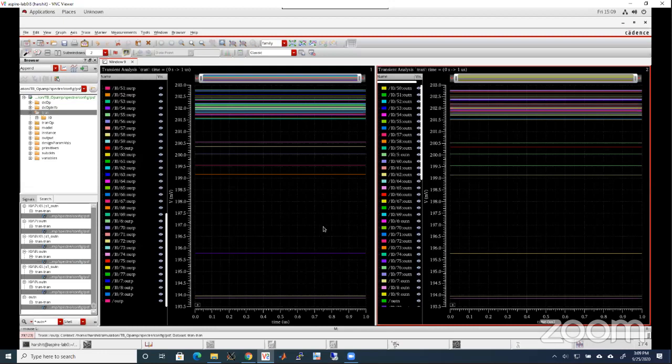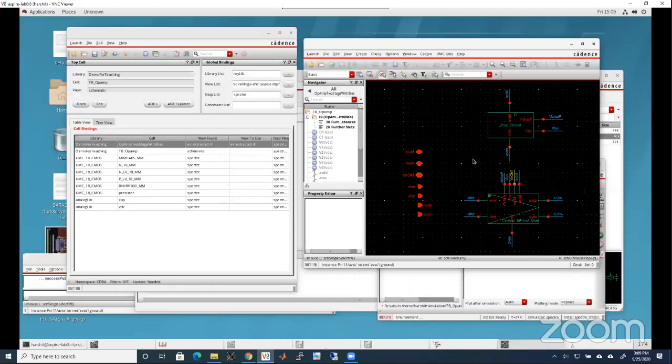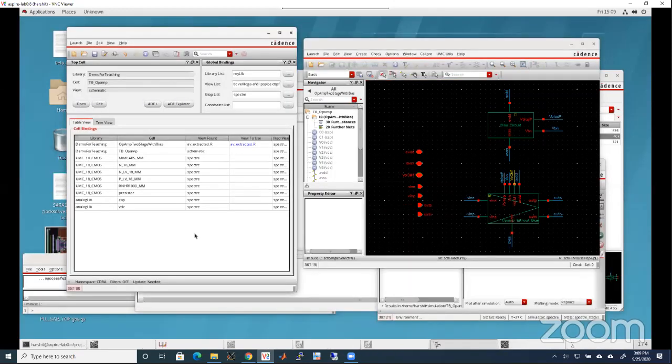So with this, if there are no questions, I'll wrap up the op-amp layout aspect here. We went from layout, DRC, LVS, extraction, different forms of extraction, creating a config view, and then using the right view in the simulation to do the simulation. Any questions so far?